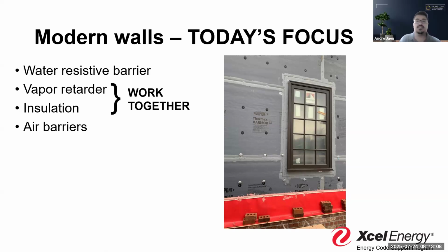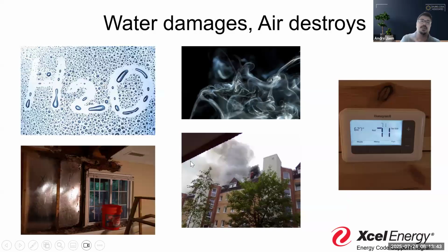So as we use continuous insulations more robustly and more prescriptively in our designs generally, we have to think about its relationship to our air barrier. Because if I air seal on the exterior and it's completely impermeable, and I also put a vapor retarder in that's so stringent that it won't let any moisture permeate the other side, well, no matter what happens, I know there's going to be moisture that's going to coalesce in those wall cavities, right? And if I didn't tell it where to go, then it's just going to hang out there. And that is where we start to develop those issues. So these two are really joined at the hip and work together in a really important format.